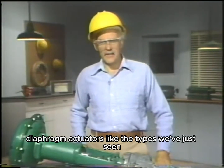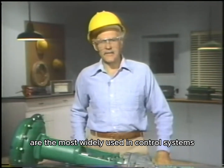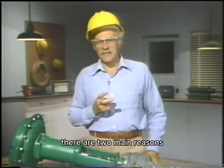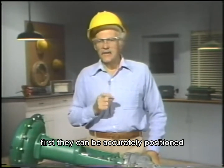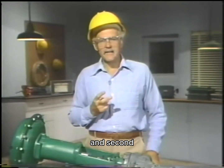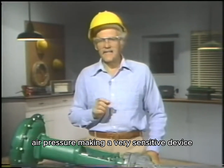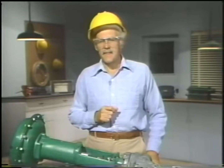Diaphragm actuators, like the types we've just seen, are the most widely used in control systems. There are two main reasons. First, they can be accurately positioned anywhere between their extremes of movement. And second, they're responsive to small variations in control air pressure, making a very sensitive device.